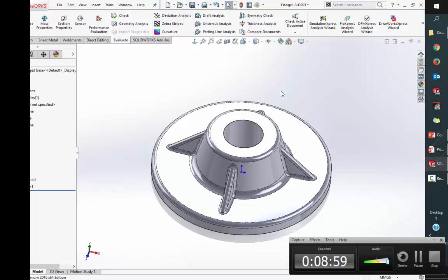And how would I fix something like that? Well, in this particular case, I might want to make the hole smaller. I'm going to go ahead and shoot the moon and say, you know what, I don't want a hole here at all. This is a very particular hole. Maybe it's being threaded, maybe it's being reamed. I want to make sure that this is a solid casting throughout, that I have good material to roll through, all right?